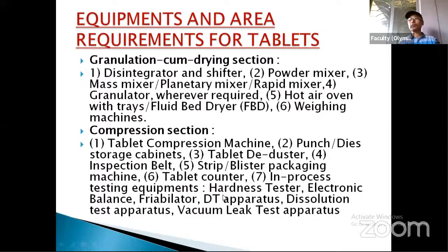But if the heating is not proper, or if your strip is not properly coated with the plastic everywhere, then you will finally get leakage. Your strip will leak through the sides. And if there is leakage, your product may be damaged. Your tablet or capsule may be damaged by humidity and the atmosphere. That is why you have to check whether your strip is properly packaged or not, whether there is any leak or not.